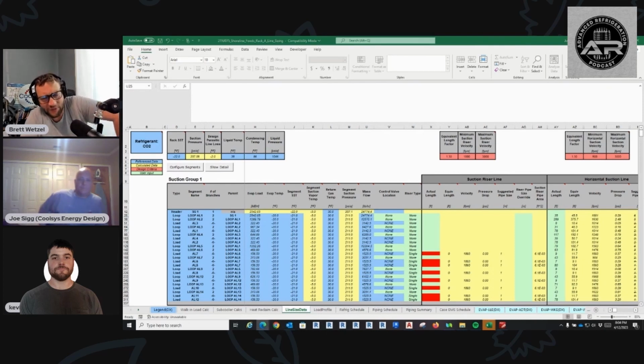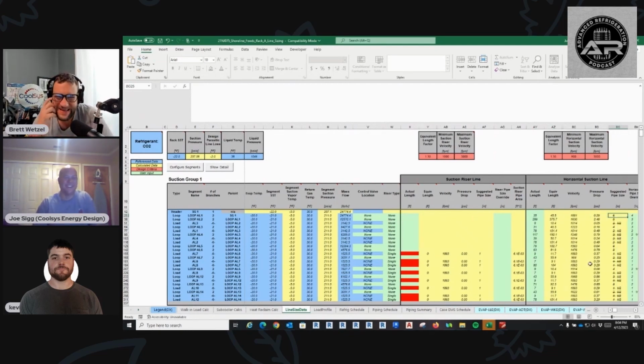Are they doing any heat recovery on any of these? No. Why? Because they have no need for it. It's a freezer distribution warehouse. So it's not like a process. There's no need for hot water. There's no AC. There's no nothing. It's a big building that's a walk-in box, basically, with some offices in the front. So it wouldn't even make sense to do a little heat reclaim. You would never get the benefit of putting it in. The ROI would be way, way out there, probably 7 to 10 years. Once you're done installing it, who cares, right?